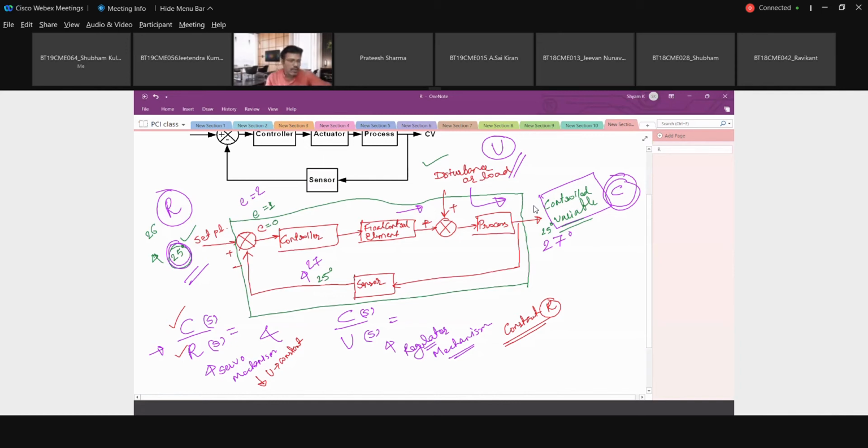Okay. So this is the example for regulator: a voltage regulator and a pressure regulator. We will discuss that. But now, if we consider the whole control system, number of blocks, summation, controller, comparator, process, sensor, as one block, at that time two arrows are coming inside, that is the set point and disturbances, and one going outside is the control variable. So how will this control variable behave if there is a change in either the set point or a disturbance, or a simultaneous change, then how will C behave. So this will give us the overall impact, the overall transfer function.